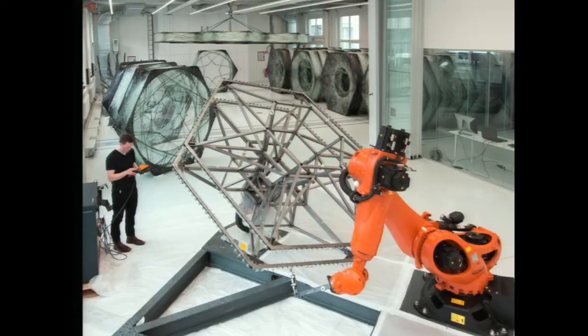So over the last couple of years, we have developed moldless fabrication processes for fiber composite materials, where we try to reduce the formwork to a very simple scaffold, as you can see here, where we actually use the capacity of the fiber to form a structure itself by continuously deforming the previously laid fibers in the build-up process.